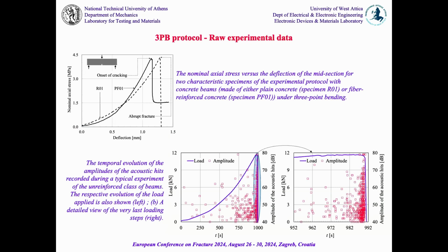We have the traditional, the expected response of the load. It is very interesting to note that especially for the fiber reinforced specimens, we have not a fracture instant because the specimen is not fractured into two parts. Due to the presence of the reinforcing fibers, we have a slow propagation of a macro crack, which means that the presence of fibers translates the very brittle concrete to a kind of ductile material, we could say. Of course, there is a standard when the conventional time fracture is considered.